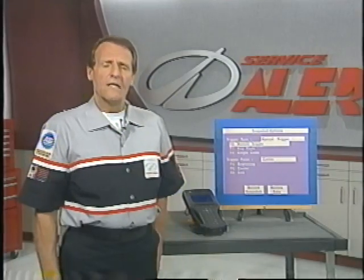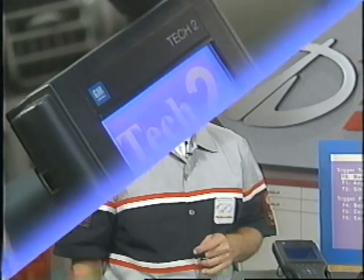For example, let's say the complaint is an occasional stumble or hesitation in a 1998 Bravada. The fault is too brief to set a code. You decide to take a test drive to try to induce the symptom and capture the fault on Snapshot. Now, the details of various Tech 2 screens will change from vehicle to vehicle and with some Tech 2 updates. But what you'll see here is close to what you'll see on any Oldsmobile.